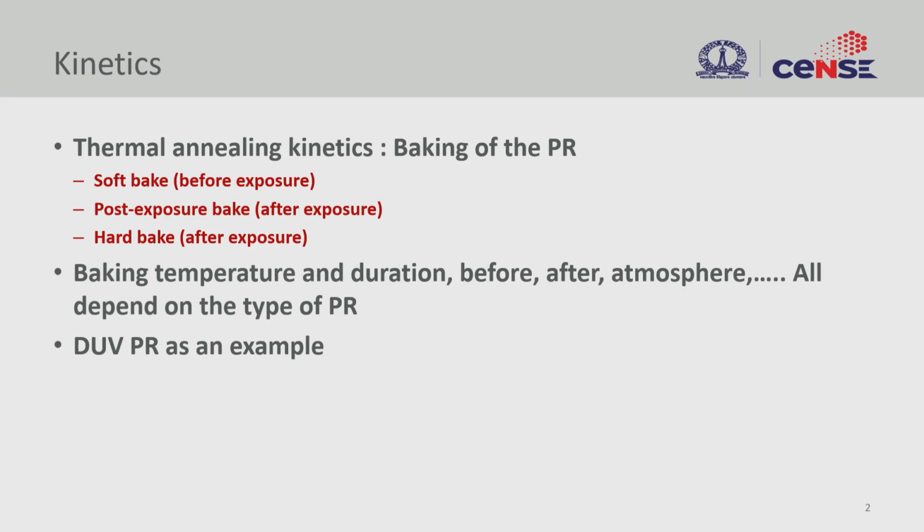But the next step, once you expose, is that we also have to bake this material. In particular, with deep UV type resist, you have to bake the material in order to keep the reaction going, or accelerate the reaction, or in some cases arrest the reaction. So in both cases you need to apply thermal energy, what we call baking.